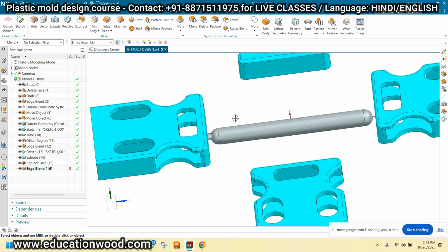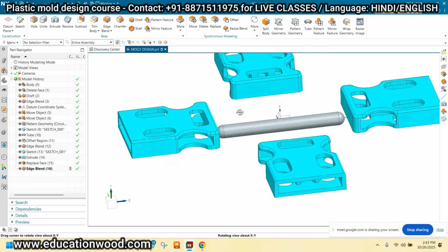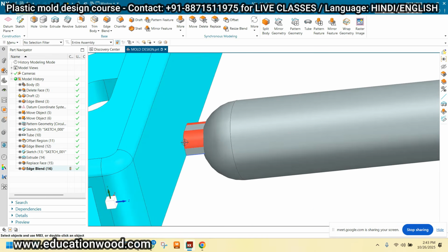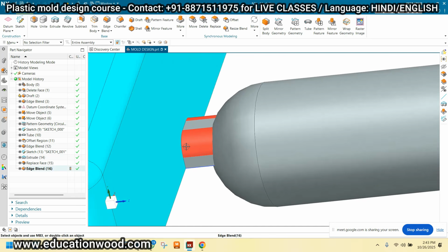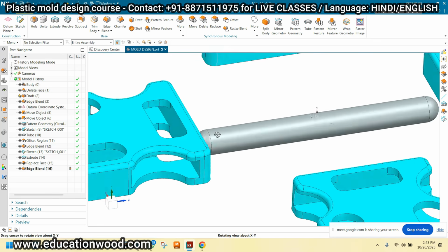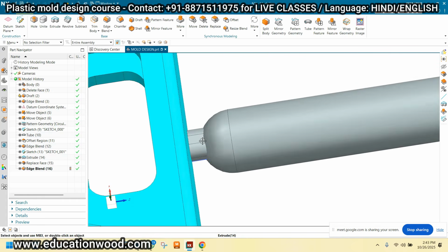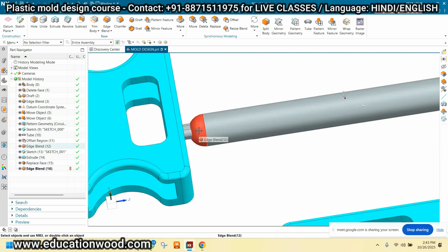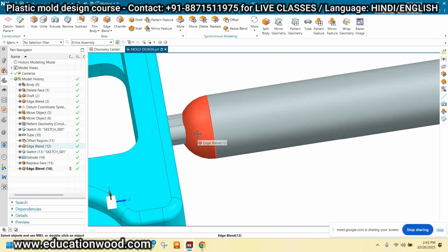No, no, it depends upon the manufacturing. For example, if you have a tool room and you have a minimum cutter of 2 diameter, you can easily make a 1 mm radius, right? So depending upon whether the manufacturing is feasible or not. But we should provide the radius, right? Because we have to apply the ball nose cutter there for making this.